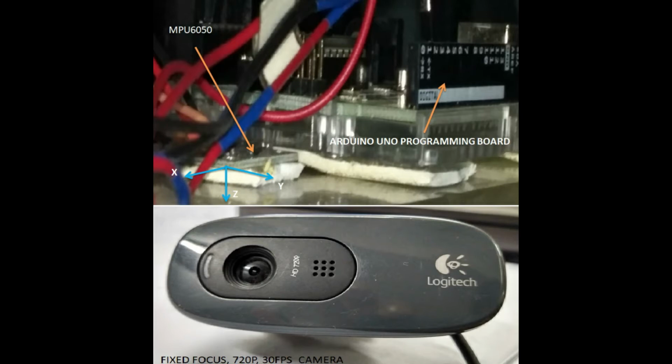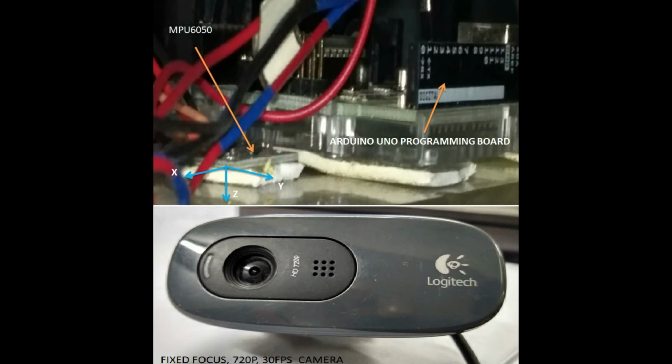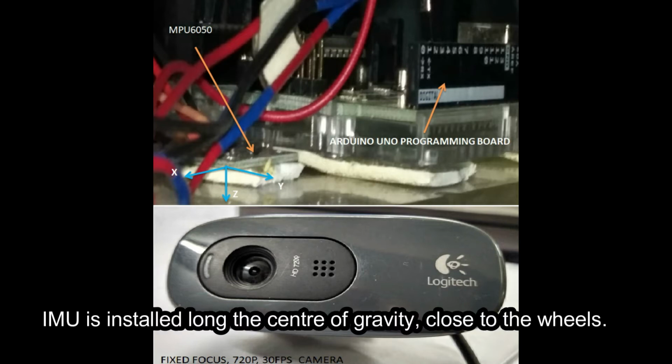Sensors associated with the experiments include a commercial-grade fixed-focus webcam of 720p resolution that can collect images at 30 frames per second. A 6-axis inertial measurement unit MPU 6050 has been attached to the chassis along center of gravity of the vehicle and has been controlled by an Arduino Uno programmable microcontroller connected to the server.